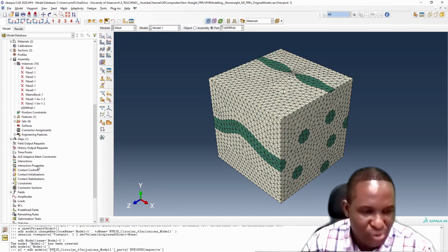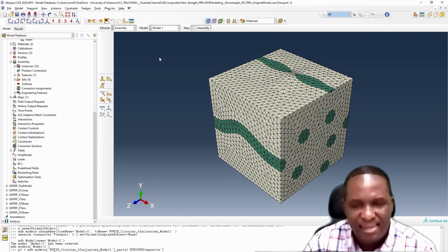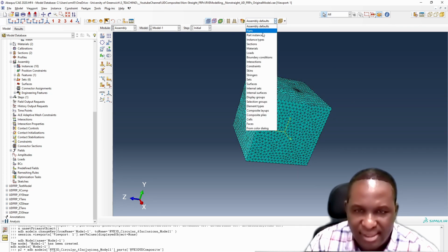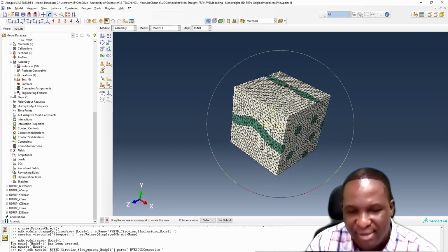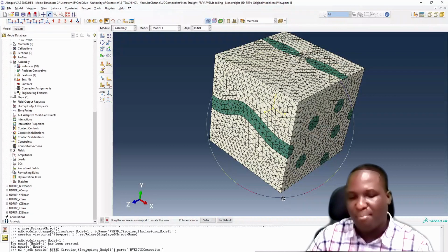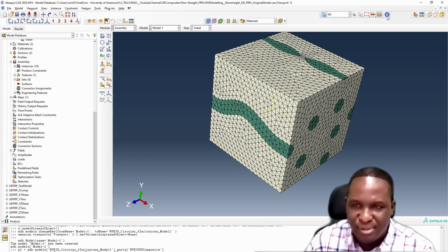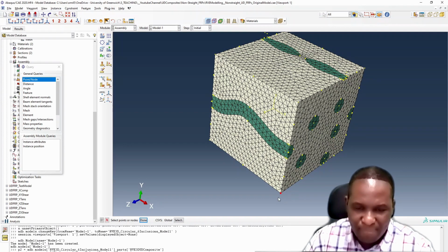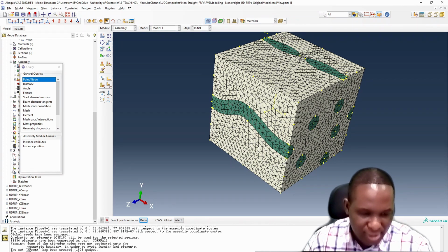The other thing that we need to do is go back and switch to the assembly module. Okay, this is the system that we're looking at and the materials. So there's the assembly module. We want to find a reference point that we're going to use to apply our load. What I usually do is apply it somewhere close here, but I need to know what that point is. So I have to query that position. I'll use the Q button. What is that point, which is here? And that is coming up here as 100, 0, 100.